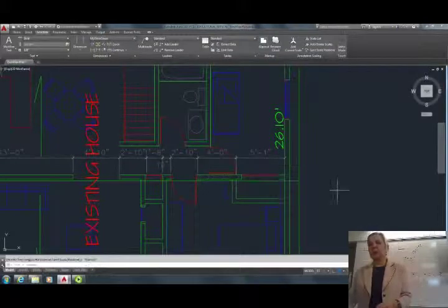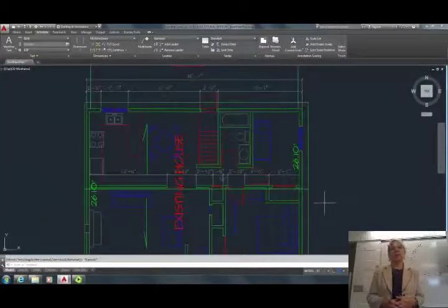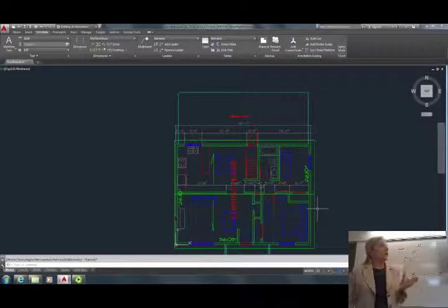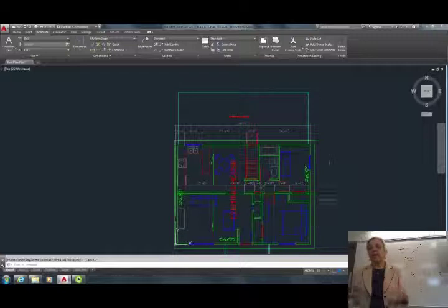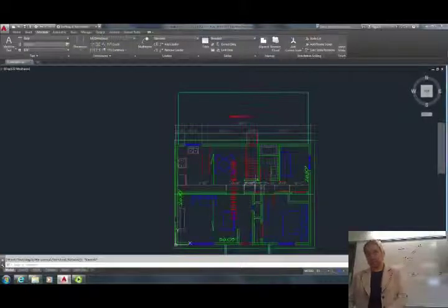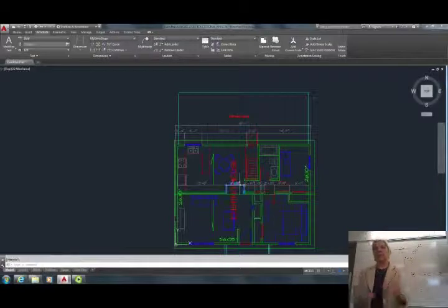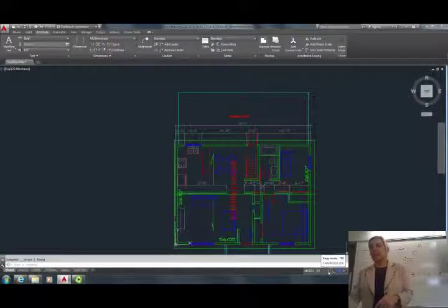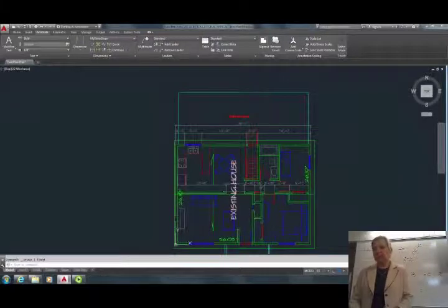Now how many dimensions do you actually need? Well, you should cover all of your new construction. So there might be 2 or 3 horizontal strings. Let's talk about something else. If you come to the area, on a real project, I would probably take 1 dimension out. Let's say I would take this dimension out. It's still a string, but what I'm telling the contractor is that 13 feet is expensive. That 13 feet is important. The 5 feet is important. Give me all of these strings. This is your leeway. Do you understand what I'm saying? Or maybe it would be this way.